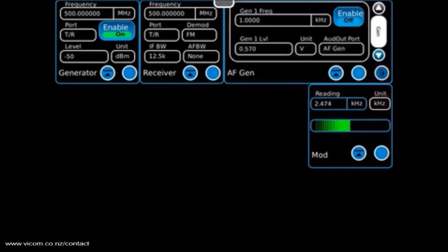The stack function allows an even greater number of tiles to be used simultaneously in a test display. Several stackable tiles can be placed into the stack. The stack icon will rotate through the stack each time it is selected. In this case, only two tiles, the AF-Gen and modulation tiles, are stacked. So each time the stack icon is selected, the display will toggle from one tile to the other. Using the grid and the sizing functions, a screen containing all of the functions and measurements for a particular test can be easily built.